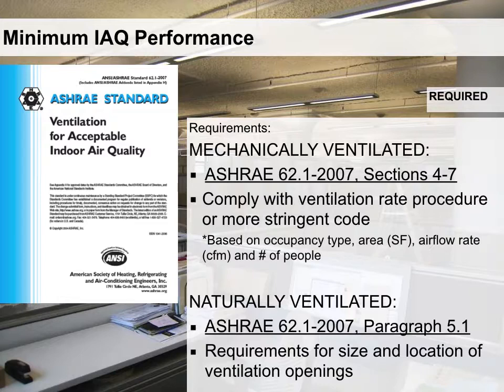A lot of the standards that they regulate are things like how much fresh air should be brought into a building at a base minimum. And sometimes they'll even vary that depending on the type of space it is. You may need more fresh air coming into a conference room because we have more people in the space than you will need in a single office.